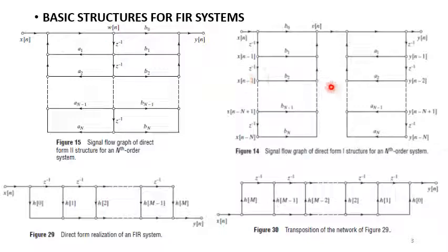Whereas in the direct form 1 structure we need almost double the memory units. Also, by just looking at the figure, in direct form 1 we implemented poles first, followed by the zeros, whereas in direct form 2 we have zeros followed by the poles.